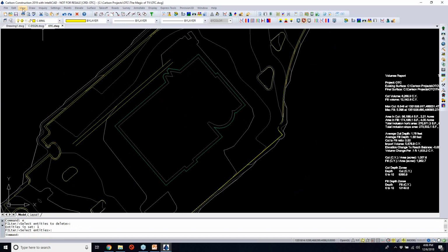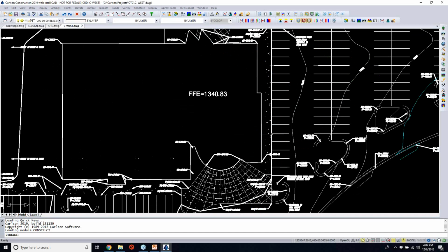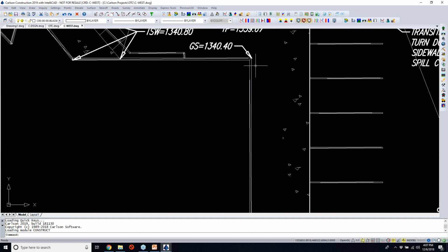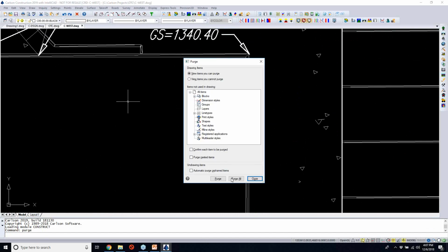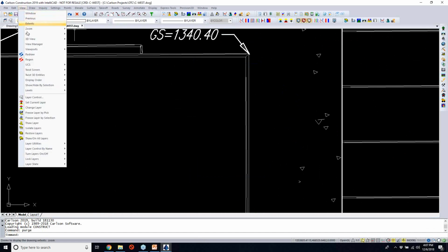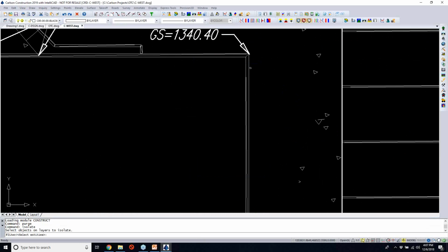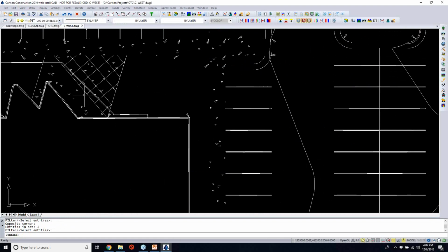So if I go back and open up the West drawing in here, originally when the PDF came in, the entities that were on here, with the way these layers were, if we go back and purge everything that's in here out of here, so this should be pretty much as clean as it is, there's not a real easy way to get to just the building outline. So if I was to say, let's isolate, view and isolate layers, and just isolate, for example, even just that single one right there, that's one entity in the selection set.